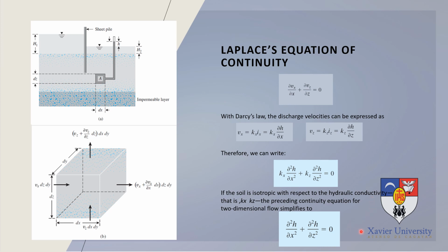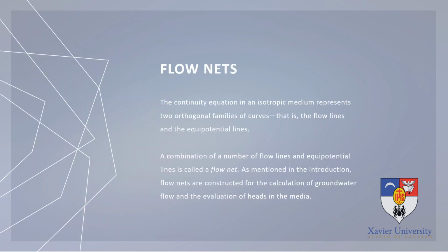So this equation can be used to solve simple flow problems or simple situations that would require us to compute for the rate of flow. So another thing about seepage is the flow nets. This is very much common when you talk about seepage. It would directly mean the flow nets, because we would calculate the seepage through the flow nets.